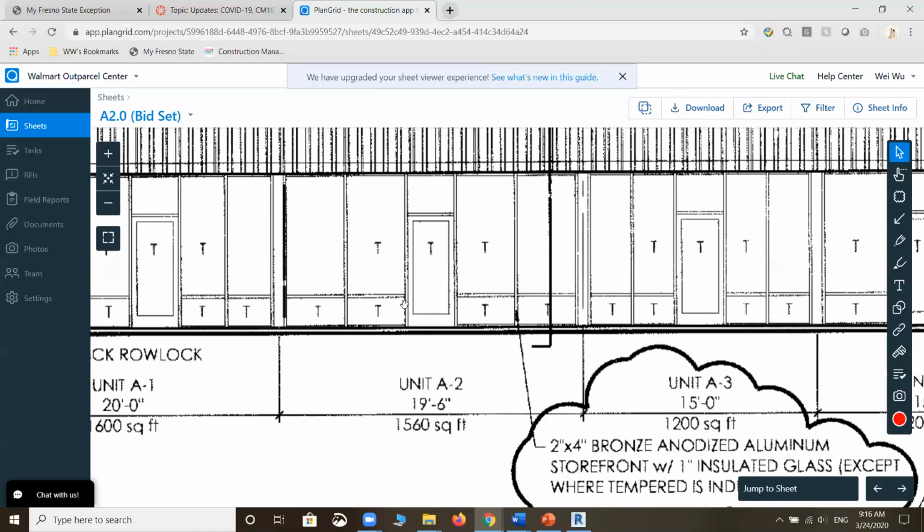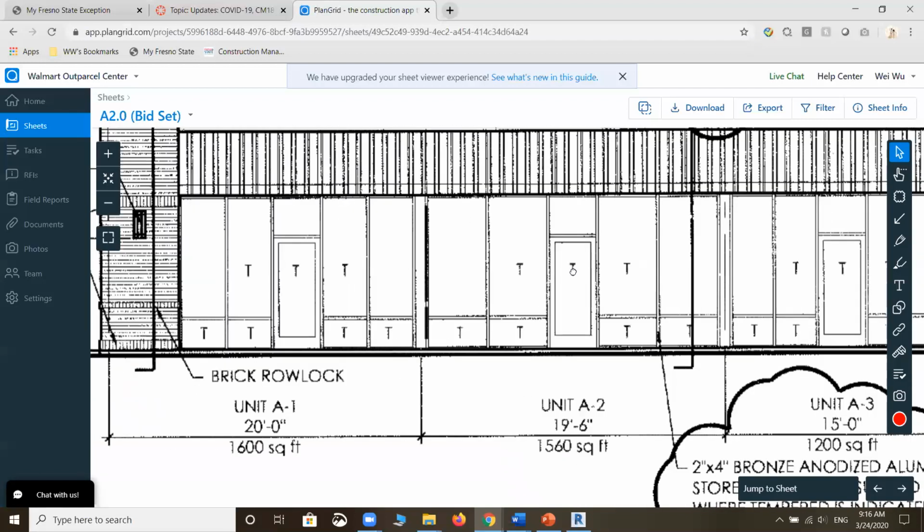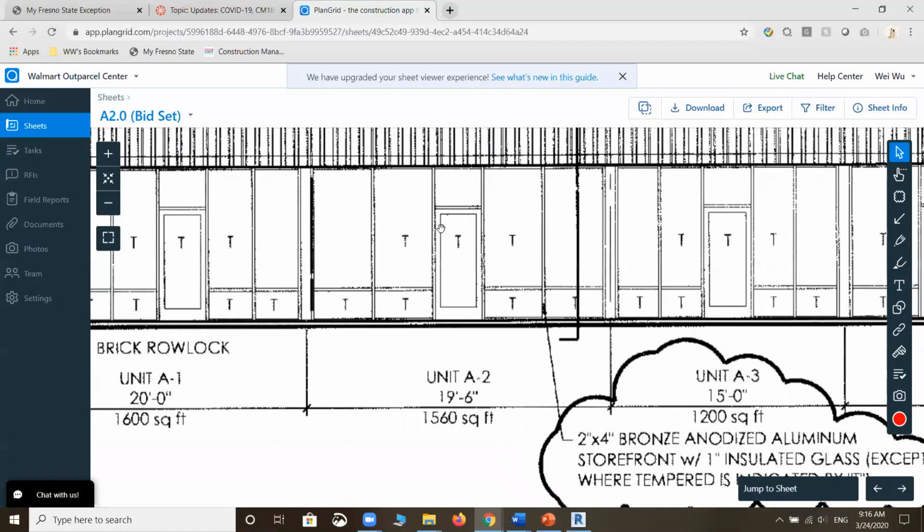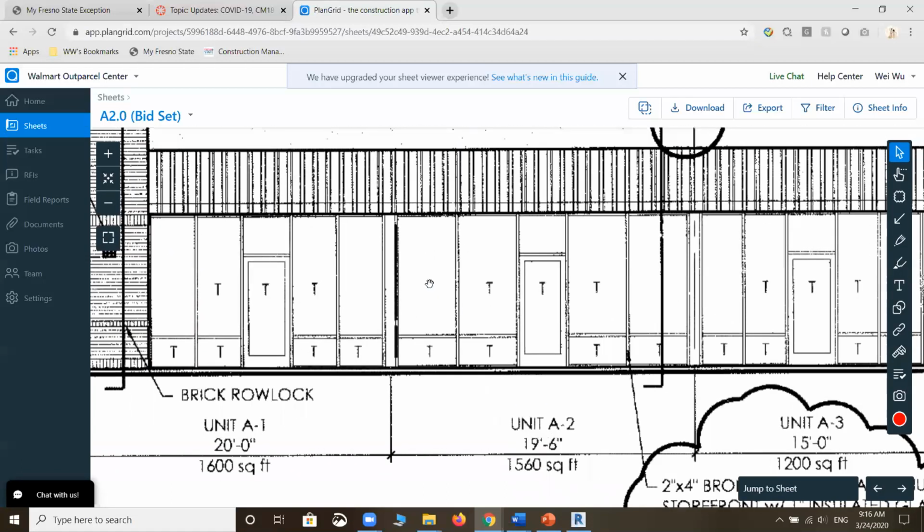To do this, we need to understand how to actually separate this panel. First, we have to determine where those edge curtain grids are supposed to be. Second, we need to put the door in the middle. Then we need to figure out how wide the door is, so that we can actually fix this curtain grid and this curtain grid. Then the last curtain grid is going to be in the middle of those two curtain grids. So that's the logic we're going to follow.